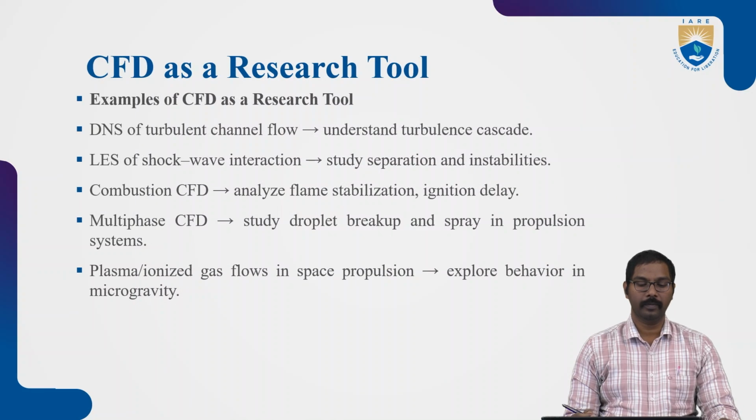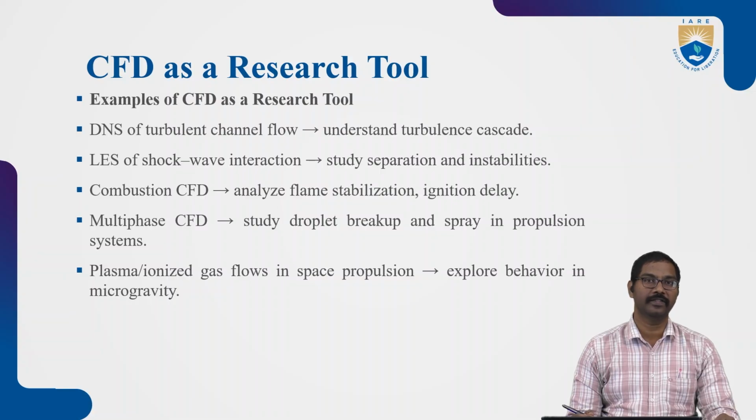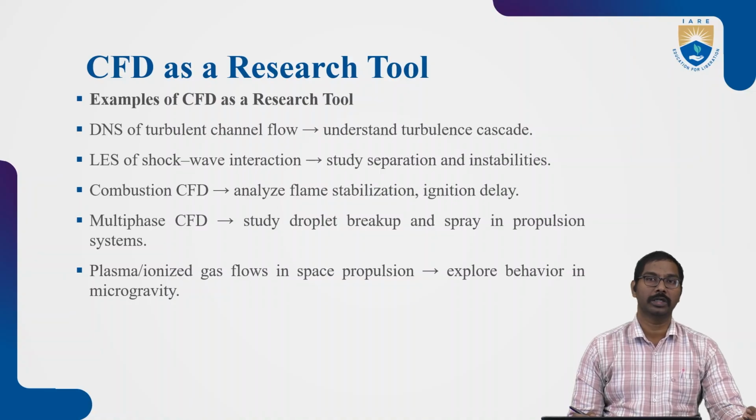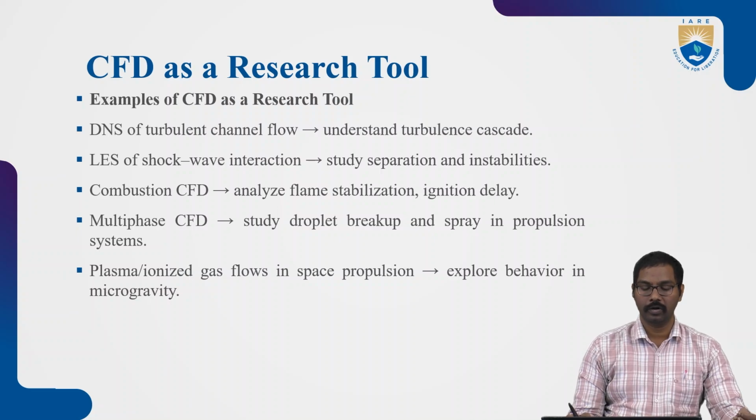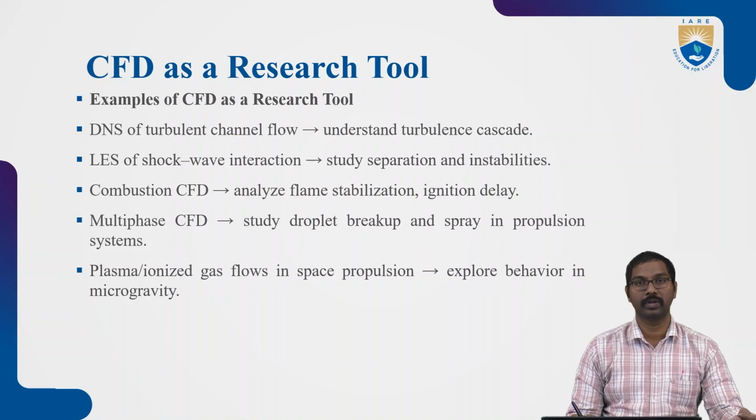Some examples where we consider CFD as a research tool are the DNS of turbulent channel flow, or the LES, large eddy simulation, of shock wave interactions, where we have to find out the separations and the instabilities, and also supersonic flow combustion, where ignition is going to be a problem, or continuous combustion is going to be a problem, or flame stabilization. We are going to use different techniques so that continuous supersonic combustion can take place to achieve hypersonic speeds. And also multi-phase CFD.